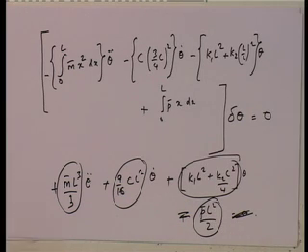Note that I have got exactly the same equation that I got by the equation of equilibrium, where I took moments about the left point to be equal to 0, because obviously at a hinge it has to be equal to 0. I have used the principle of virtual displacement, where all I have done is I have given a virtual displacement that satisfies all geometric boundary conditions, and I have just taken the virtual work done and put it equal to 0. And so, I get exactly the same equation.